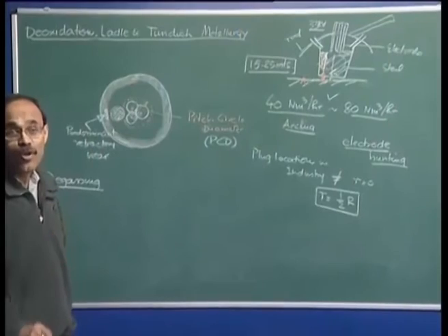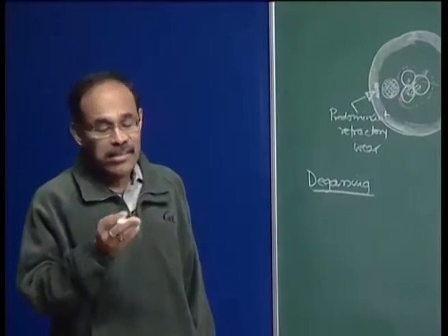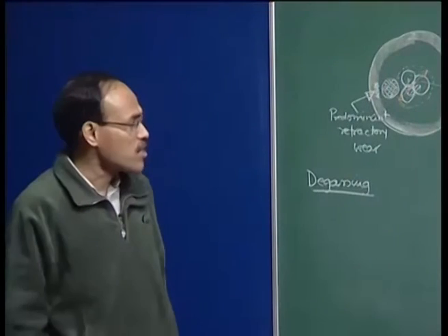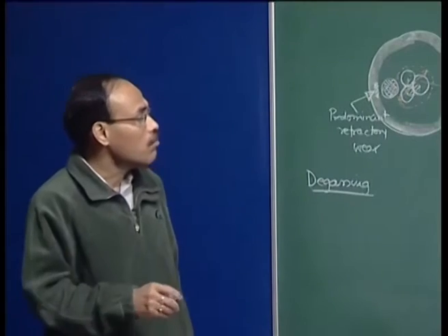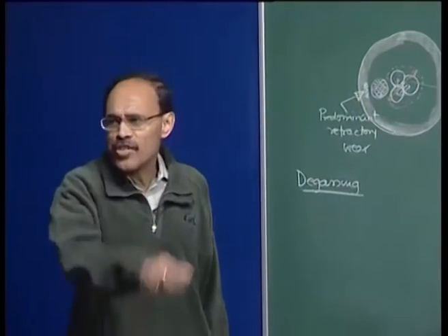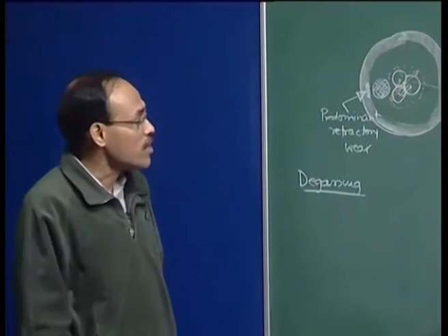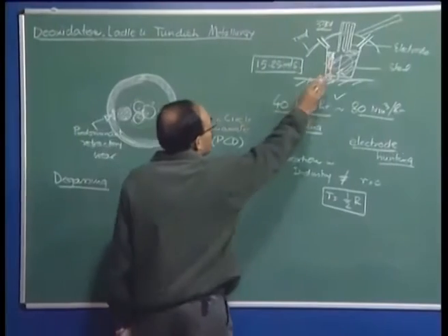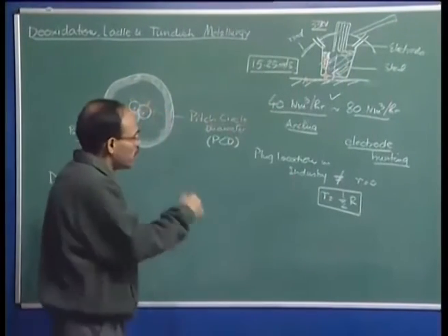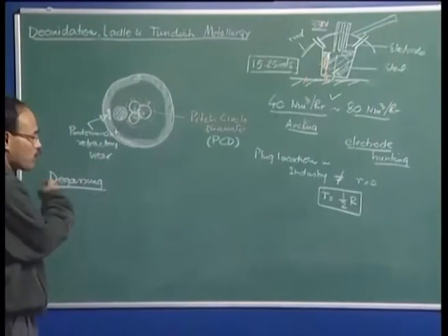Hydrogen and nitrogen, we all know that hydrogen causes embrittlement, nitrogen impairs toughness of steel very drastically, and also if you are talking of making a deep drawing steel, in that case a significant amount of nitrogen is not tolerated. So, at this particular stage, even beyond the ladle furnace, we may have some nitrogen and hydrogen, which have to be eliminated.